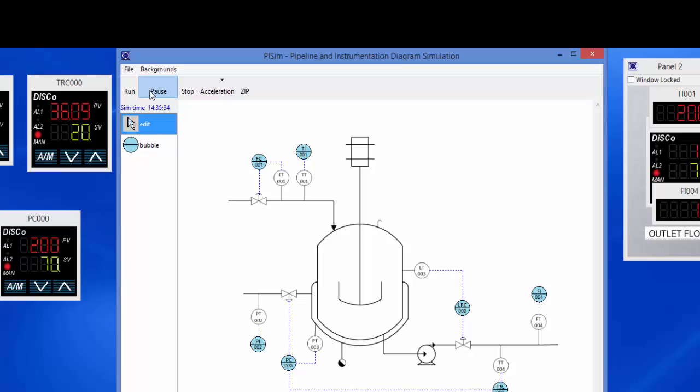What's happened here? Oh, I know what's happened. It's because we're actually still running the simulation. When the simulation's running, editing's actually blocked, so you can't actually do things to it. So we'll just stop it there and then try and drag a connection across. Okay, so that's the cursor over an output port.